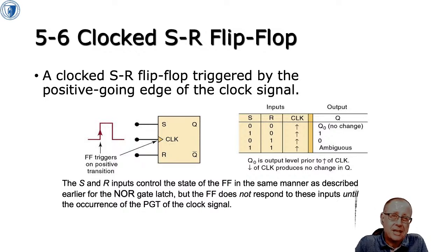One thing you need to be clear about is that on this clock input, there is no bubble, right? There's no dot on the beige coloured box. If there were a dot there, then that would be a complementary input or an active low input. Because there's not, it's a standard input, so it's an active high input.